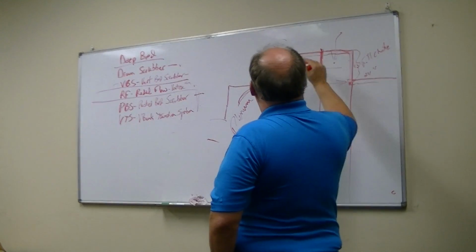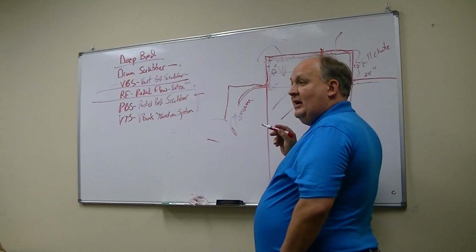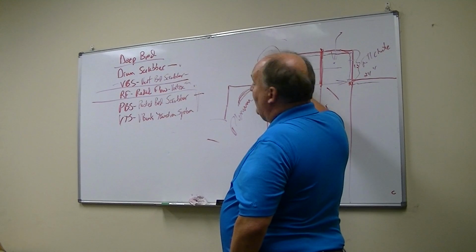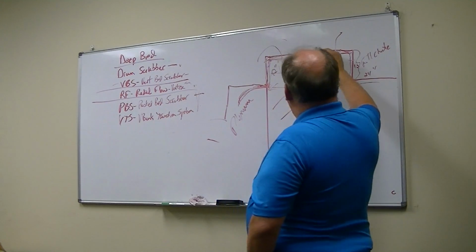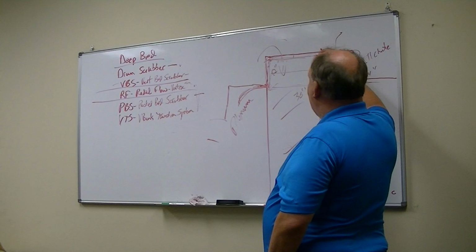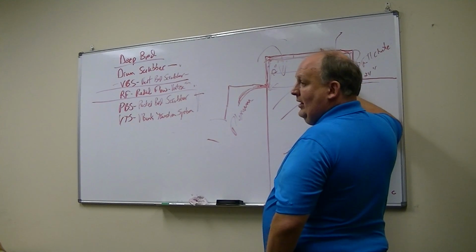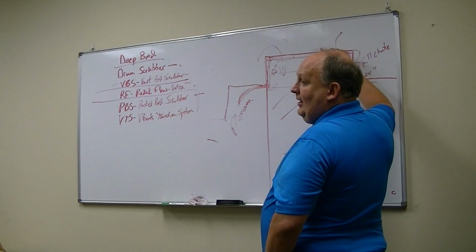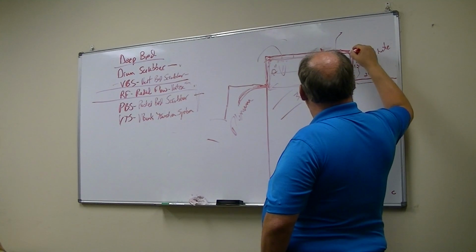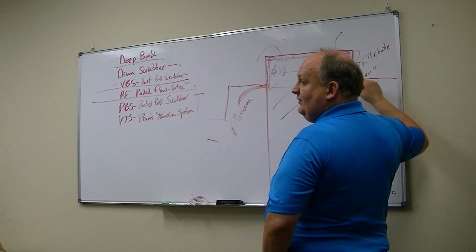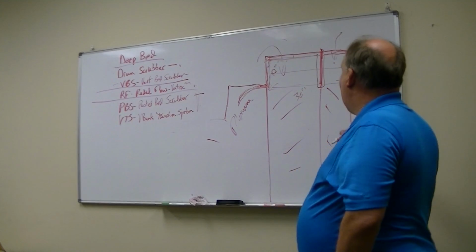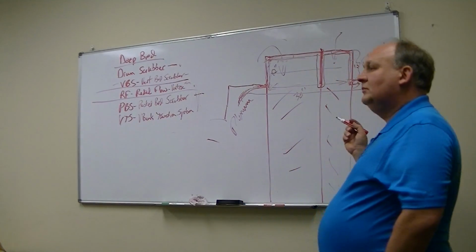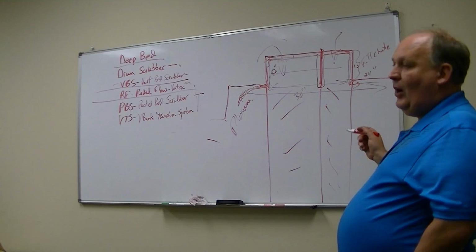So now if you've got a 1-inch gap, what does the air want to do? It says, all right, I'm going to go up here, I'm going to try to cheat, I'm going to go up through 12 inches, and then I'm going to run, oop, boom, I ran into this. Now how do I get out of here? Well, the only way I could go down is to go through here, add another 12 inches, go back around, come back up, that's another 12 inches, go back down and go back around. There you go, that's 48 inches now, right? It's going to say, oh, that doesn't make sense. My GPS is telling me to do this, right? So that's how we prevent that.